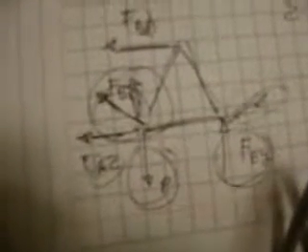So we make the summation of forces in the y direction equal to 0. Then you go: force Ey minus P plus force BC, the thing we're looking for, times opposite over hypotenuse, so this is a sine.